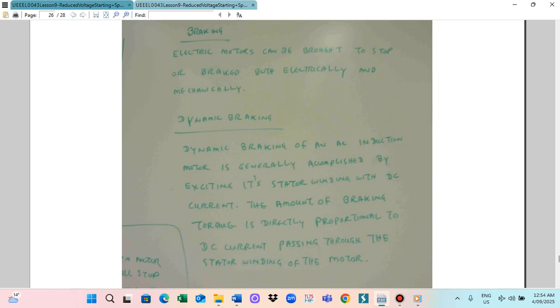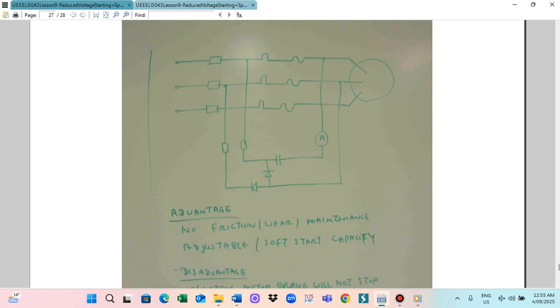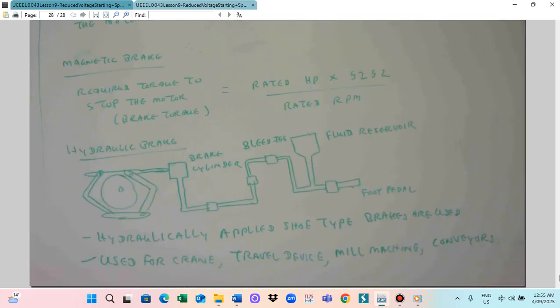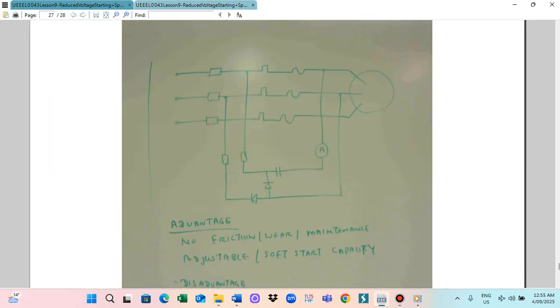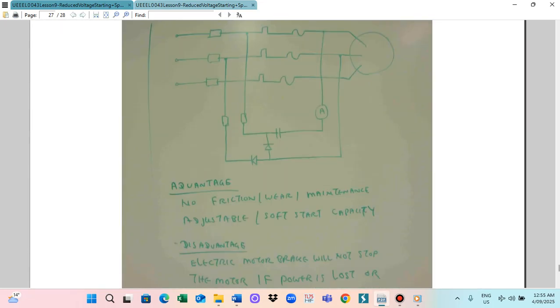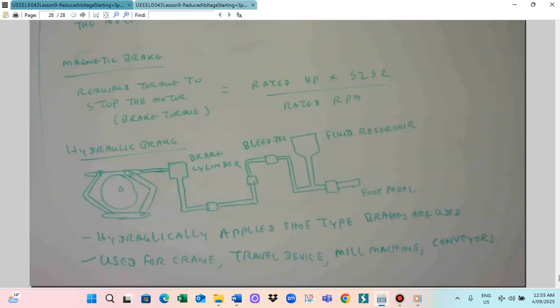And another one is the electrical brake. Hydraulic brakes hold the brake right at the same time. And another way also uses the electrical braking system. Electrical braking means that when the motor is running, as soon as you press the stop switch, we provide a DC current. So DC current flows into the motor, so the motor will stop immediately. So this is why there are three kinds of braking: mechanical brake, electrical brake, and DC supply brake. So there are three systems.